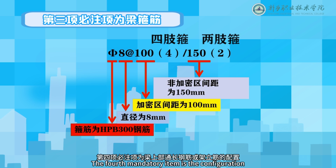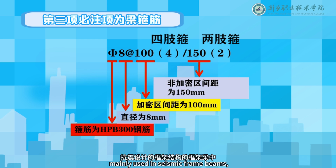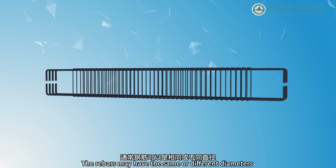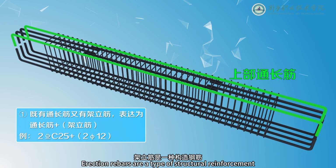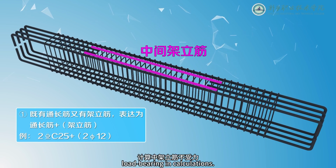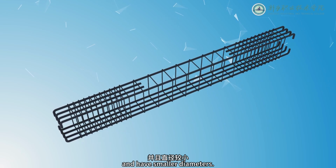The fourth mandatory item is the configuration of continuous top longitudinal reinforcement or erection rebars. Continuous longitudinal reinforcement is load-bearing reinforcement, mainly used in seismic frame beams, or in continuous beams of non-frame structures where required by the designer. The rebars may have the same or different diameters, and may be spliced, mechanically connected, or welded. Erection rebars are a type of structural reinforcement used to facilitate tying of stirrups. Erection rebars are not considered load-bearing in calculations. They are generally placed in compression zones of beams and have smaller diameters.